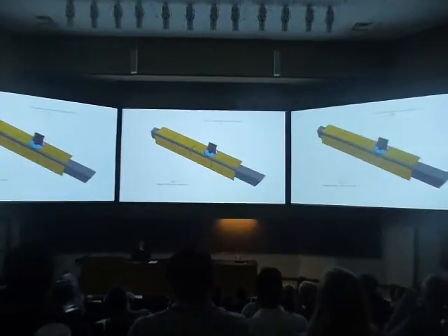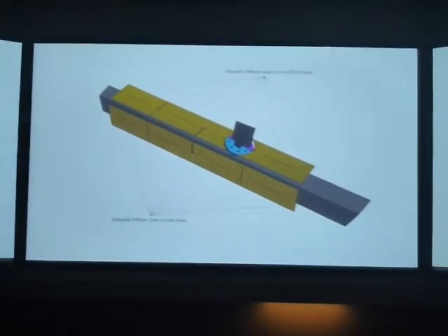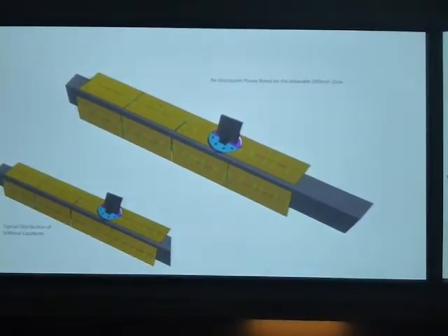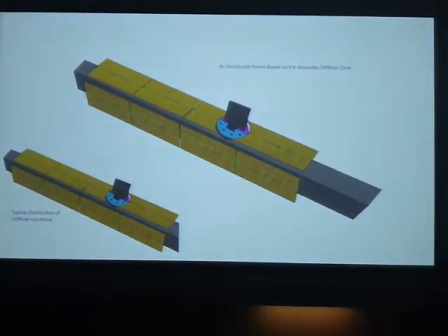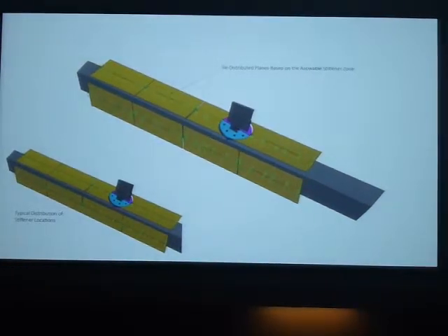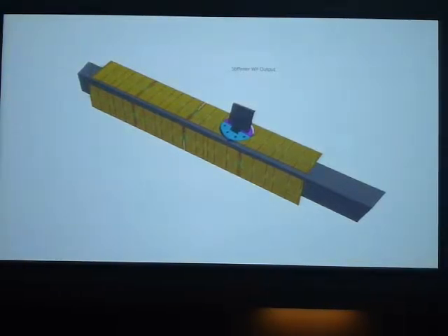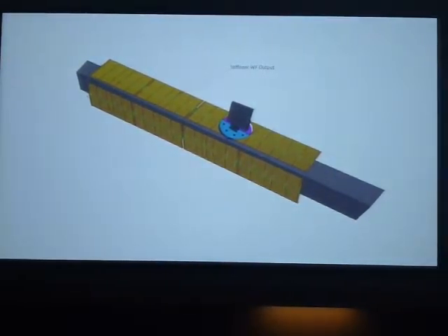And so the resulting curved pieces now indicate where stiffeners can actually go. Any stiffeners that are no longer positioned on these curves will automatically be repositioned. The plane definition will be stored as a user attribute inside a point object in Rhino. Again, in a separate Grasshopper session, these planes, as derived from these point attributes, will be used to create curves to represent the shape of the stiffener object.